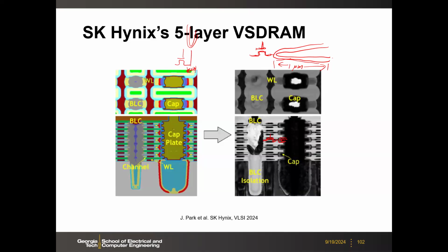So here my question is that, from the footprint point of view, this horizontal 1T, 1C actually is not very attractive, right? If you think about the dimensions here, maybe you only have 20 nanometer. Here you have 1 micrometer already. So what would be the selling point for this approach? You can stack enough so the density for 1 micrometer is greater than if they were stacked vertically.